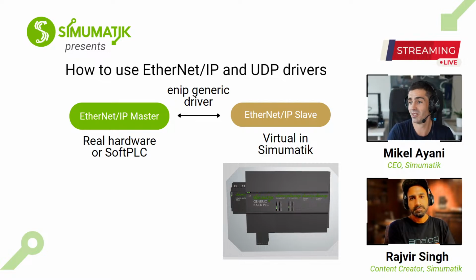So as you were saying, the PLC, whether it is a real PLC or a soft PLC, will have the address of the slave, which Simumatik will emulate, and will start trying to make a connection, and once the connection is established, we'll share information. So that's the cool thing. This is the opposite way to what we have been doing with the native protocols, trying to read and write in the PLC. This time, with this driver, we don't actively do anything. We just wait until the PLC tries to communicate, and then we answer with the same telegrams that the real slave would. And that's the cool thing.